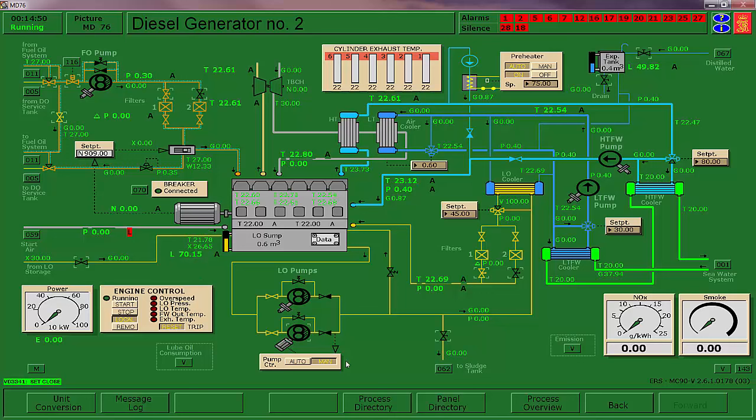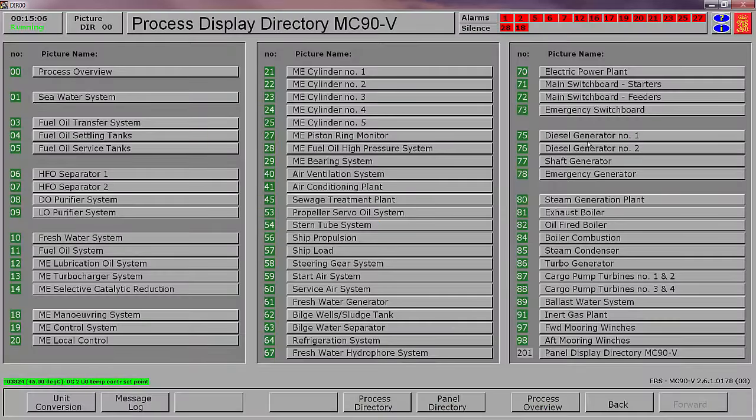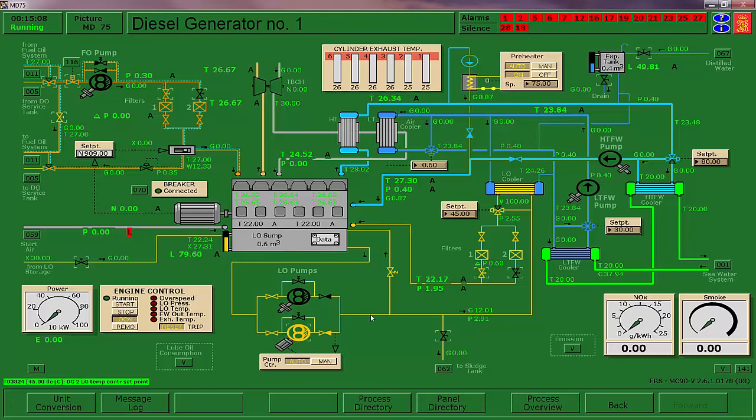Okay, 70 is where I wanted it. We'll put on our lube oil priming pump. Fuel's good, lube oil's good. I've got pressure, I've got flow, 45, 30, 80, preheater on. So we're good. All right, I'll double check my main diesel generator again real quick.